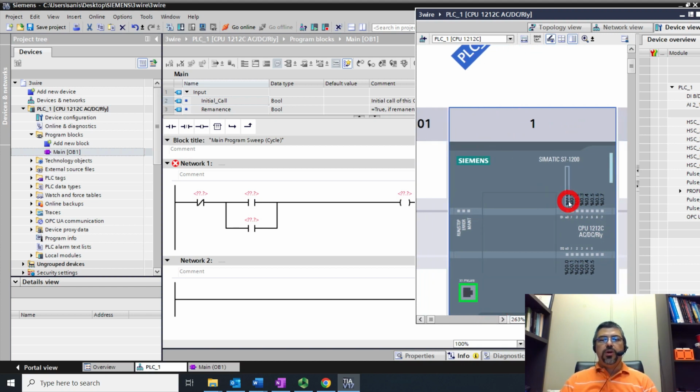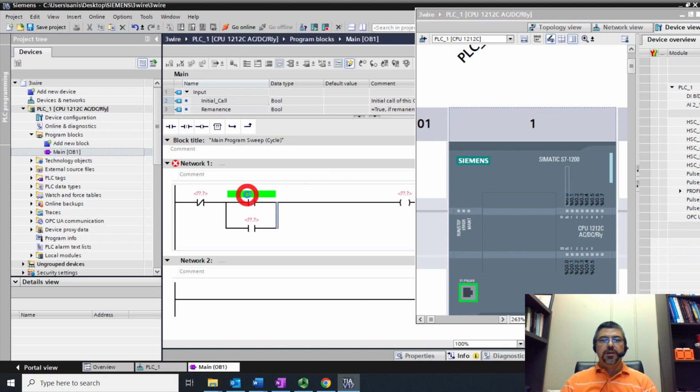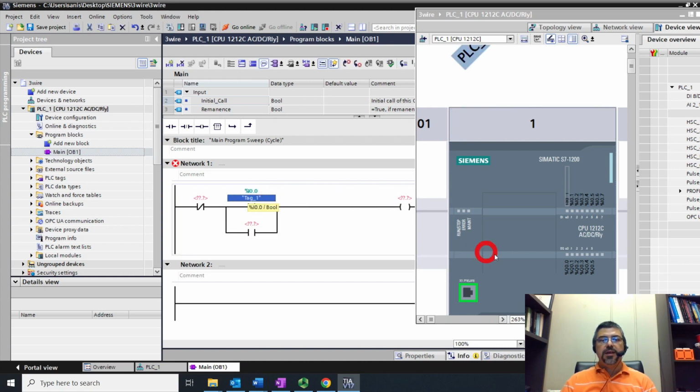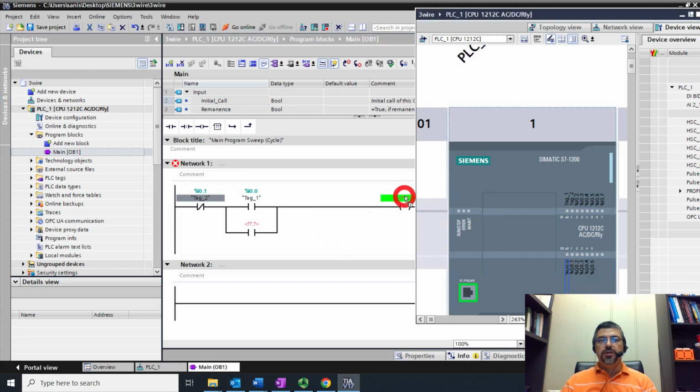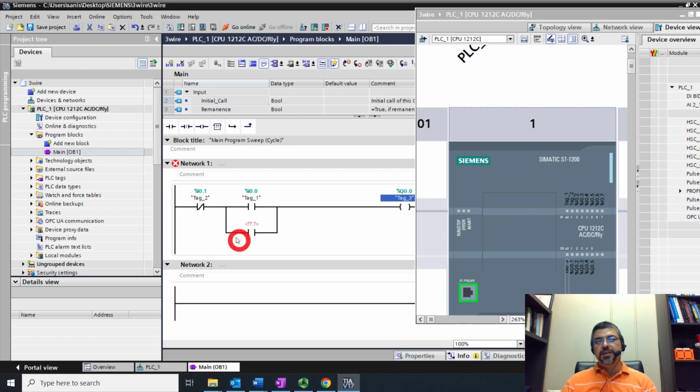Okay, so as usual, I don't know which one you want to be start and which one is stop. If you want, the first toggle will be start. So let's put the 0 on the start. Then if you want to have the stop as a second toggle switch on your PLC simulator, let's put that here. That means the first one is start, the second one is stop. I will change the names later on. We have one output, which is output 0, put that here. And see, this one is interesting.